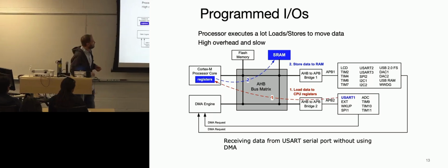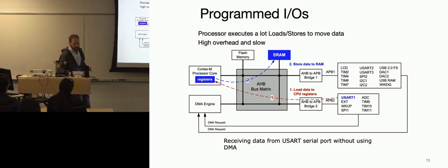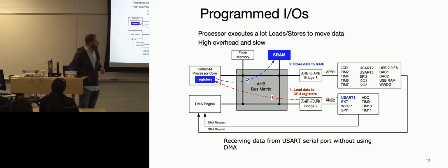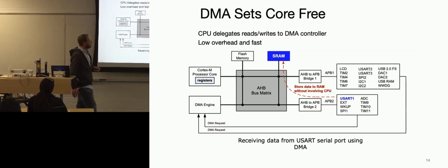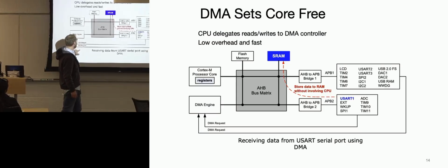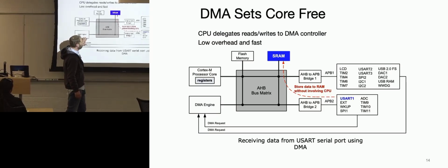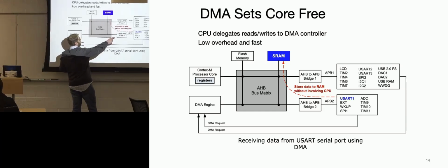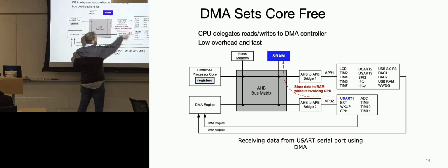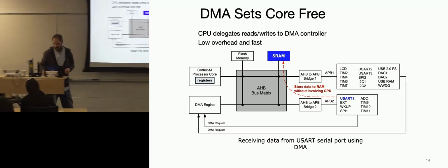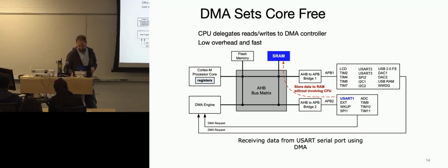And so, as a quick walkthrough, this is the counter example of what you don't want. You don't want to go to the core, so here you can send data directly through the DMA engine, where the DMA engine is controlling the interrupt request. So a lot of this is: get an interrupt from UART, okay, that's going to happen. Then it tells UART, okay, send it to SRAM, and then that can all happen autonomously. So there are good tutorials. It takes a little while to set up, but it's not too bad.